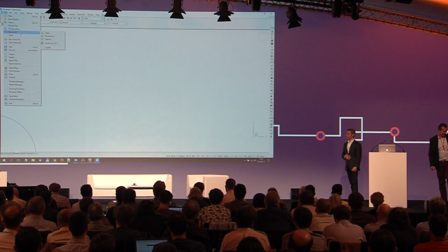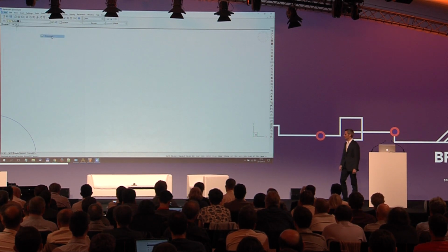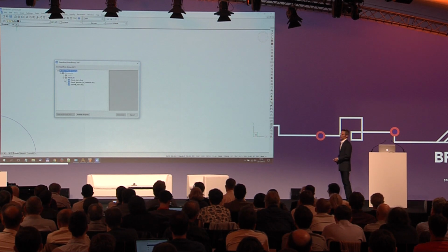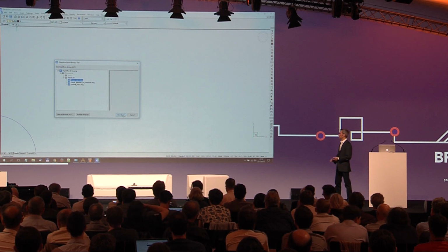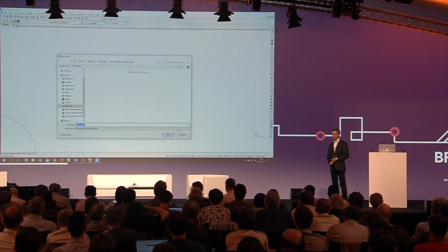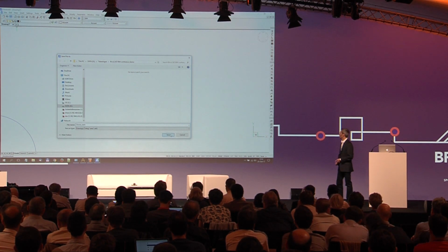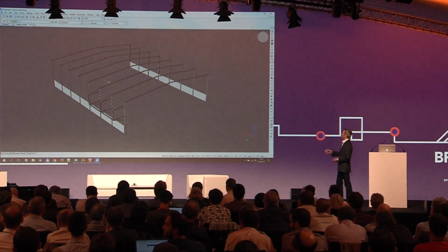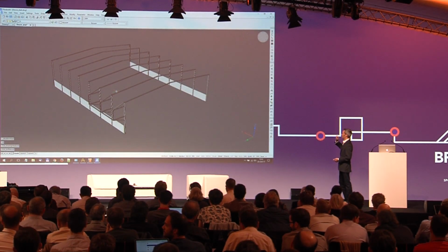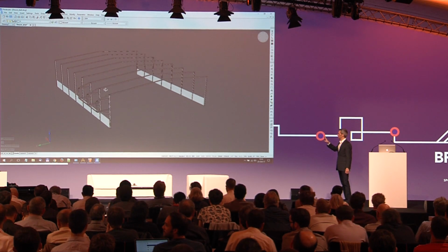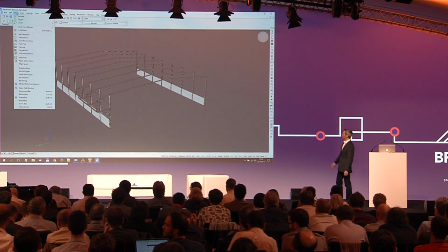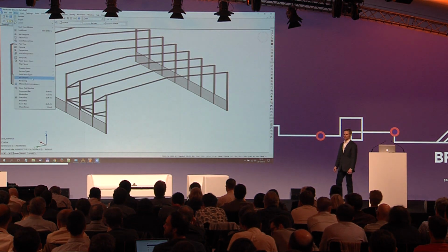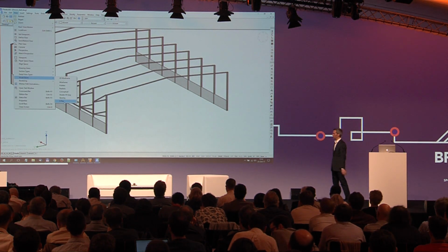So what we do is we detail the full structure and generate automatic output from that. So we don't want to start from zero, so we use the BIMified model. And we have an API to access all the BIM data. And we call this data LOD 200, level of development 200, because it is design stage. And we make LOD 400, fabrication stage, which means ready to be built.